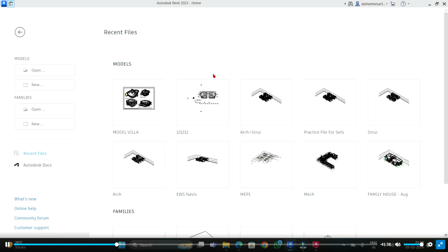So if you are working in that sort of an environment, then you need your Autodesk ID for it. Every person who is working in the BIM environment has to have this ID, and it's a unique ID for each individual. No two people can use the same ID for the project. Each person a unique ID. So that's very important. Only if you have this ID, you can work on a common data environment. You can use Revit otherwise for modeling purposes, but for work sharing mode, for collaborating in the process, you need this particular ID.